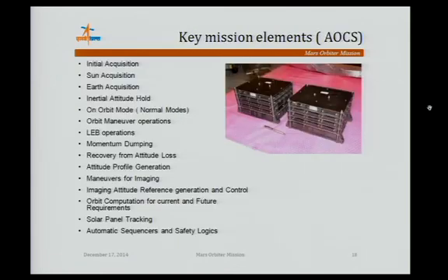If you take the AOC software, these are the major modes adopted. Most of the modules are taken from earlier heritage, and specific modules for FDIR, that is fault detection, isolation and recovery, and Mars recovery mission, basically a recovery sequencer. Those are the major modules added specially for Mars.